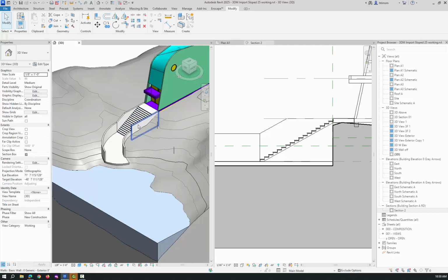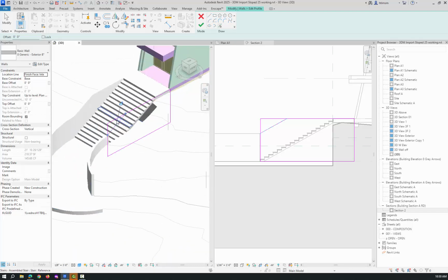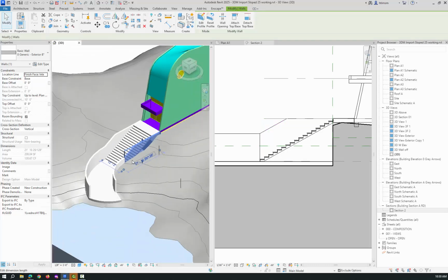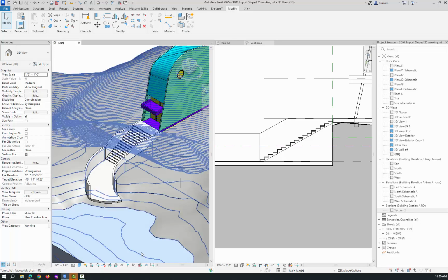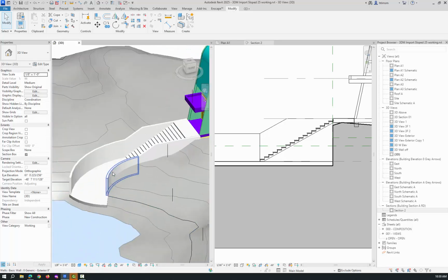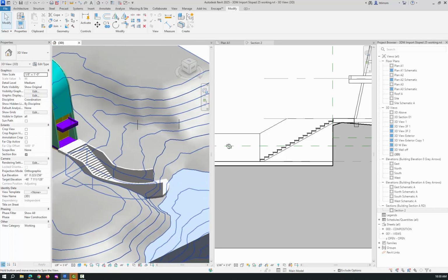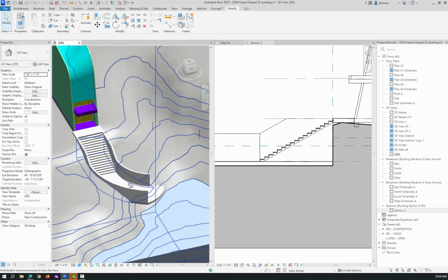And then I can pick this one and edit that profile. And I'm going to use the pick line and just pick this guy, and it will project it over to that plane. And I will trim that out and hit check. Right, so now I've got those guys. And the next thing I want to do is, come in and let's take a look over here. Looks like we could slope this one kind of down, to 3'6" there.